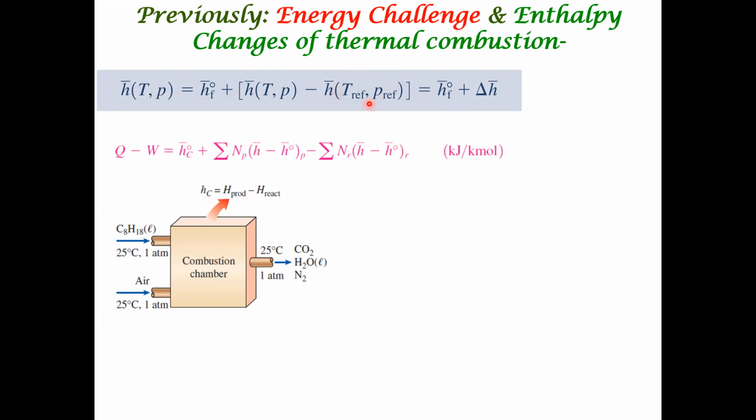That is the enthalpy of this state, okay, vapor, that is the heat of vaporization. And then you may be dealing with water vapor at a higher pressure and different temperature. That corresponds to this particular term. Okay, so you should understand the meaning of this term. It's very critical. And then the rest of the things follow.